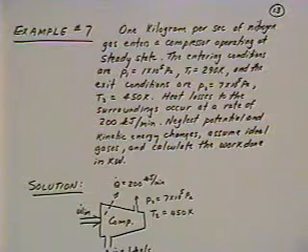The compressor is operating under steady state conditions. The entering conditions are P1 equal to 1 times 10 to the 5th pascals. This is not kilopascals now, this is pascals. That is roughly atmospheric conditions. So one bar, or 1 atmosphere pressure, is equivalent to about 10 to the 5th pascals.